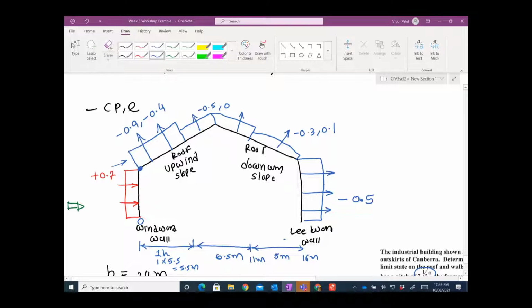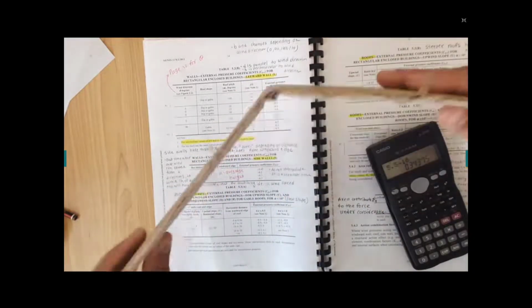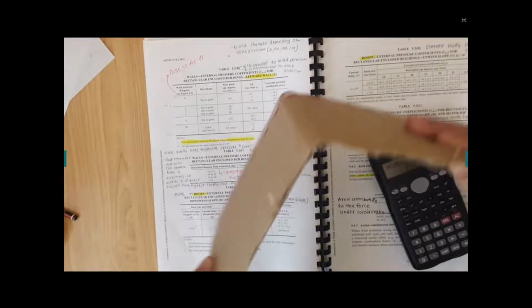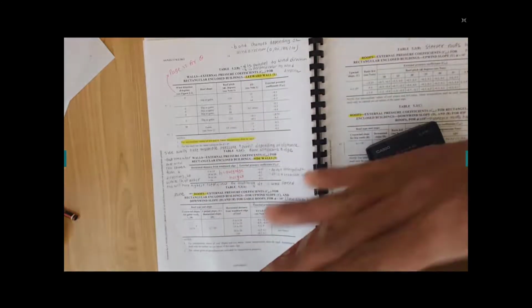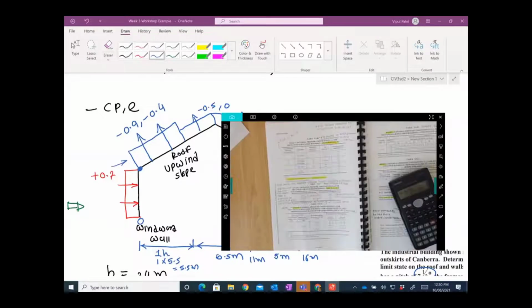And why are minus 0.9 and minus 0.5 two different values? You might think that when the wind hits the roof, it goes like this, minus 0.9, minus 0.5. The roof does not just stay still. You will see it shake, so it will have waves. Therefore it's considered two different values, and which one to select depends on when you combine with internal pressures, right? When you combine with pressures, you consider which of these values creates the worst case scenario, then you pick that one.